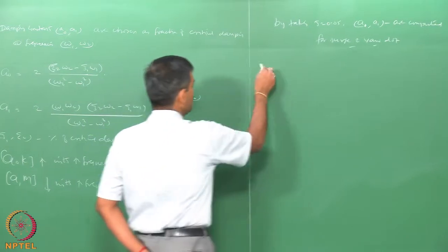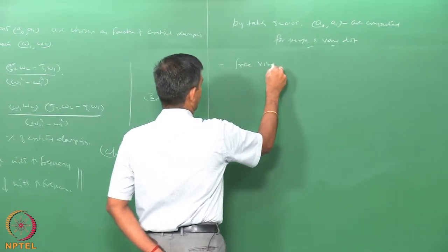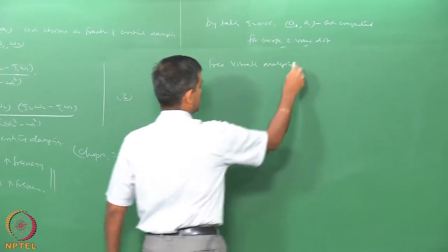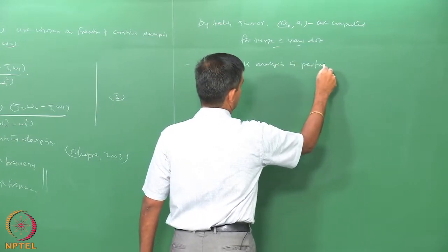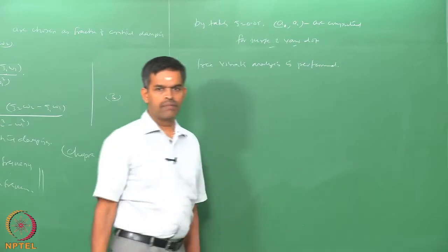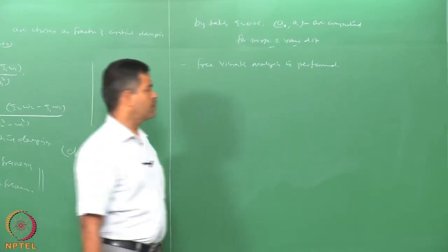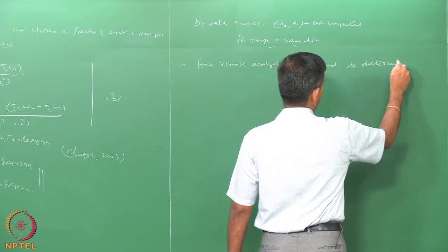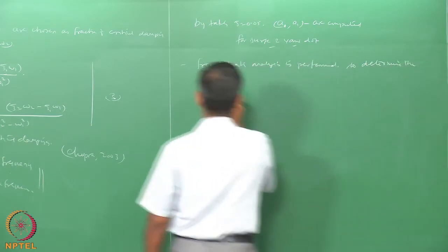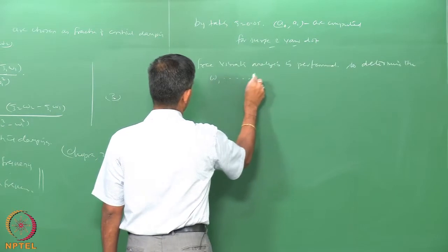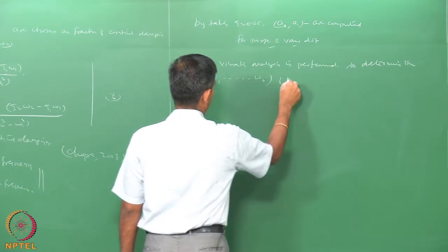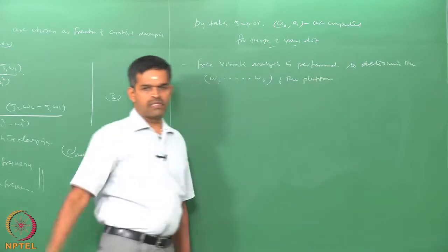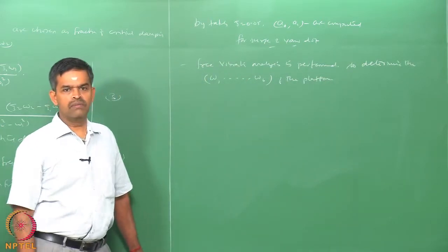Then subsequently a free vibration analysis is performed, okay, to find out the natural frequency of the platform, which can be used here for our calculation.